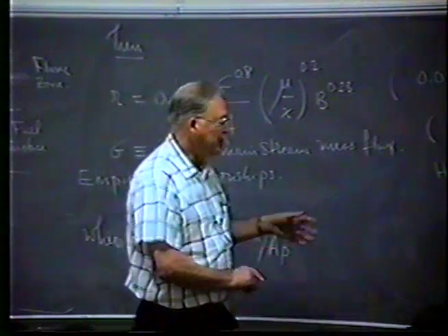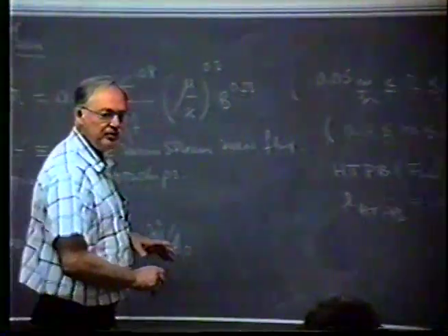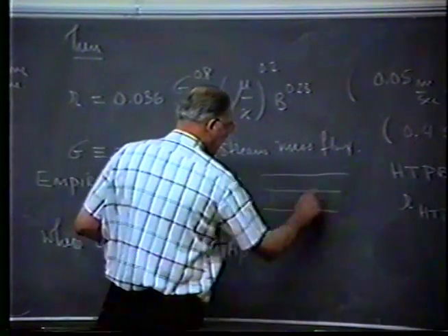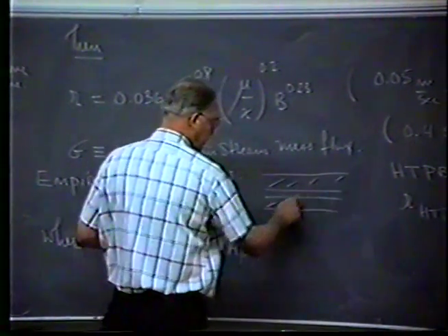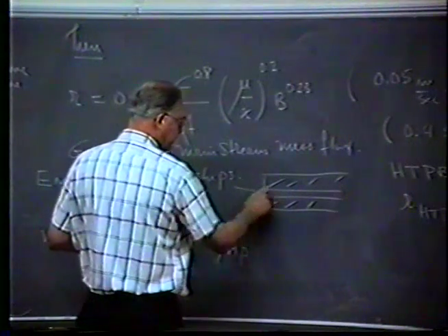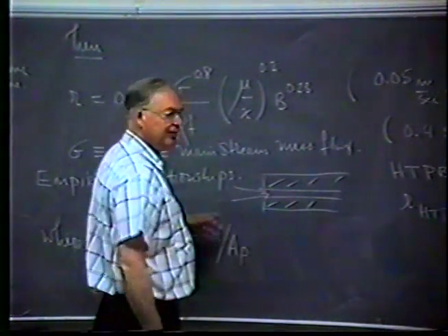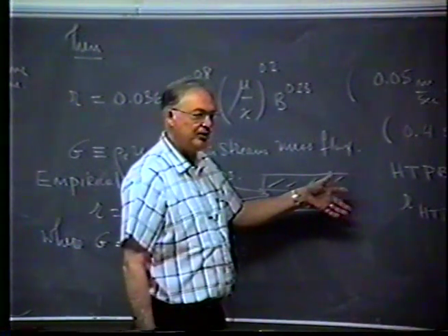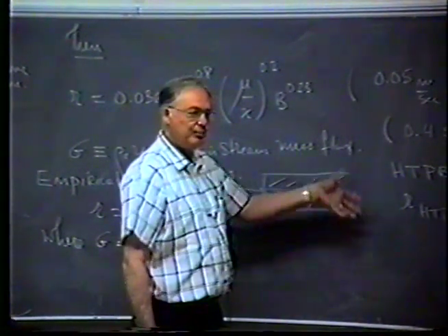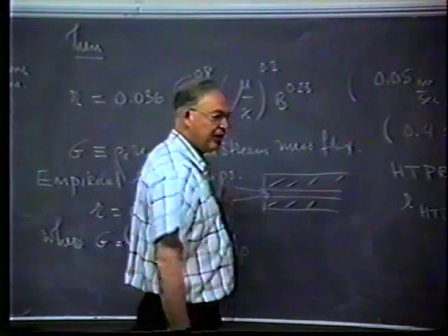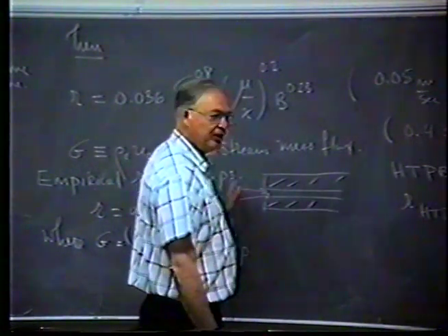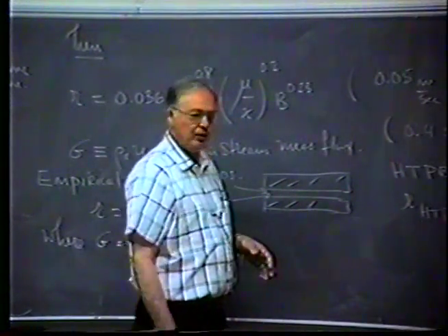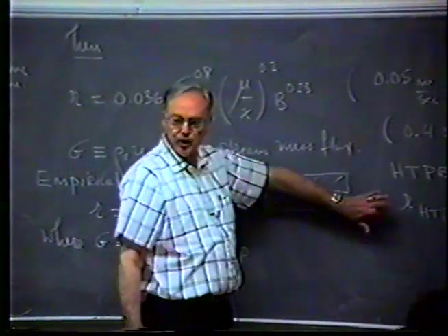Now, the implications behind that are pretty severe. Because if you've got a long grain like this, you've got a port coming down. Here's your fuel, and your oxidizer is coming in. If you don't have enough oxidizer, by the time you get down to the end here, you're not burning anything. I mean, you've just got a combustion product. So you have to have enough excess oxygen so that it gets to the end of the grain. Now, the implications are quite extensive.